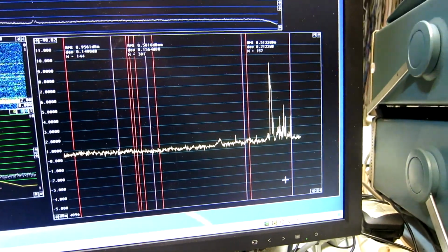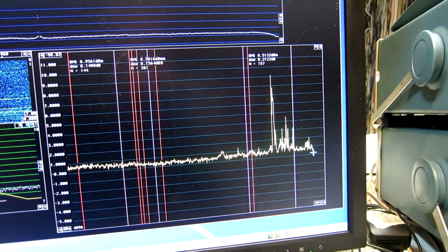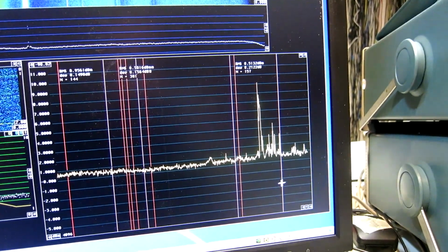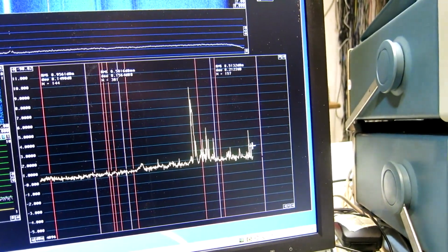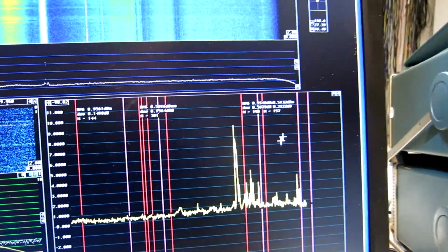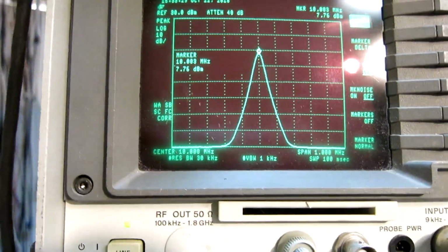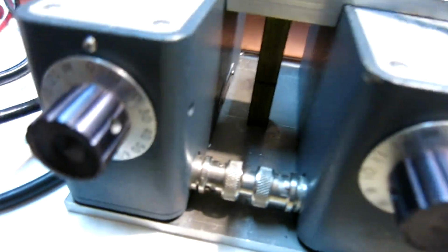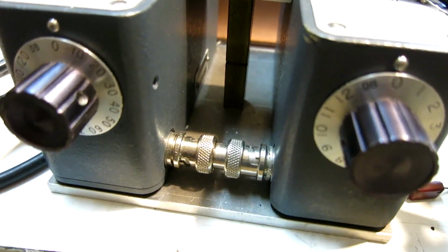Well, that was unfair. I have just been waiting a little more, and here we had some bursts of noise. So I think I will take this region in time and say it's 0.95 dB instead. The power is 7.8 dBm, and that's for an attenuator setting of 0 on both sides.